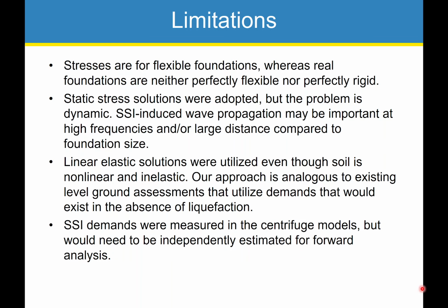There are limitations of our method. We're aware this is not a perfect method. So I'll just go over a few of those limitations here to end. So first, the stresses are for flexible foundations. Real foundations are not fully flexible or fully rigid, right? They're going to have some finite flexibility. The stress field beneath the footings are going to vary, and they'll differ from what we have here.